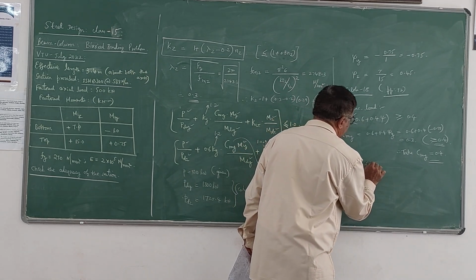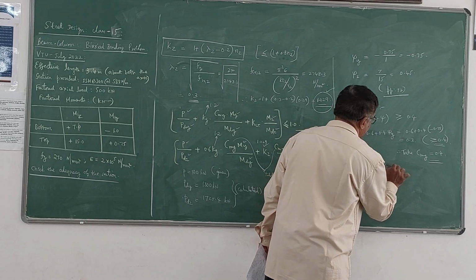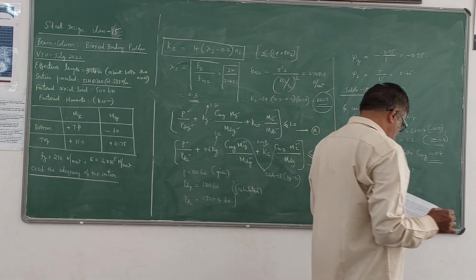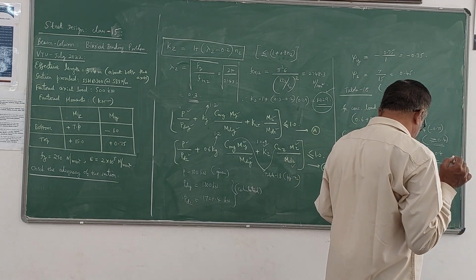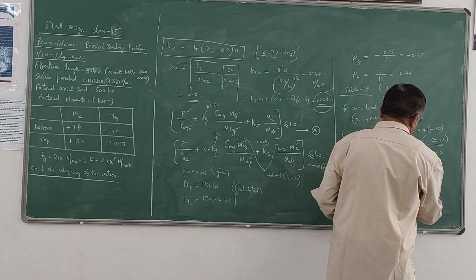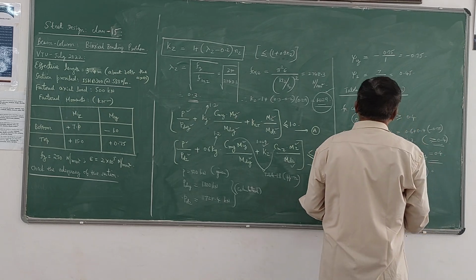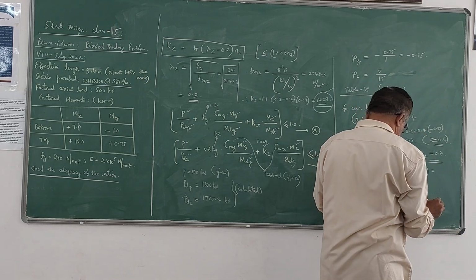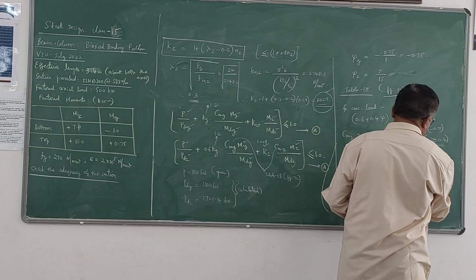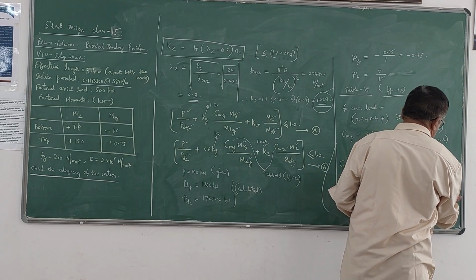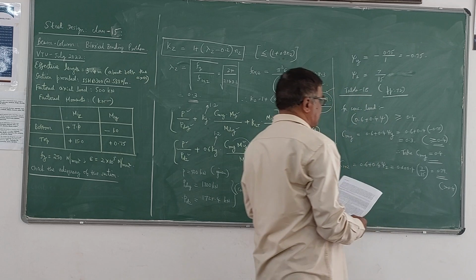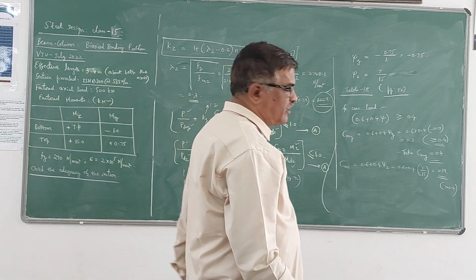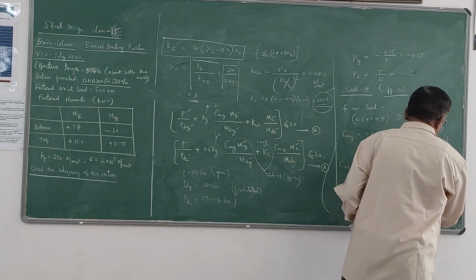CMZ is the same thing: 0.6 plus 0.4 psi z. So it is 0.6 plus 0.4 into 7 by 15. So whatever you take, 7 by 15. So this value will be 0.79. So definitely this is greater than 0.4. So the thing is, if it is less than 0.4, restrict it to 0.4. If it is greater than 0.4, whatever value you get, that you will take. So CMY is this, CMZ is this.